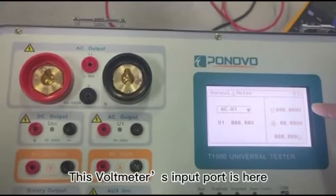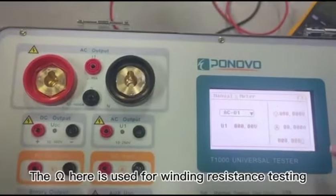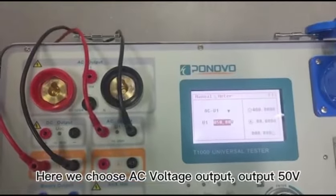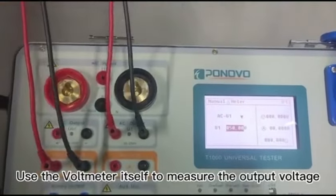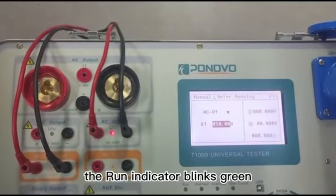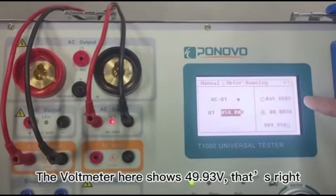This voltmeter's input port is here. This ammeter's input port is here. The ohm here is used for winding resistance testing. Here we choose AC voltage output, output 50 volts. Use the voltmeter itself to measure the output voltage. Press run button, the run indicator blinks, the AC output indicator turns red, the voltmeter here shows 49.93 volts,